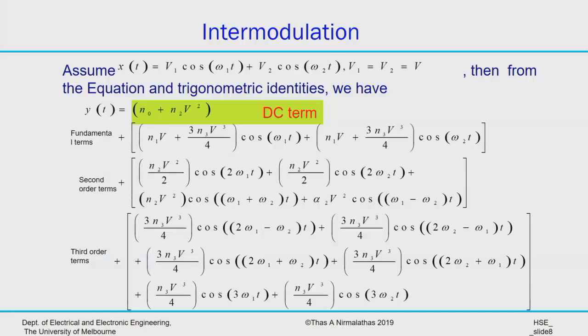All right. So as we expected, the coefficient in front of the gain of this fundamental signal is the same as what we had before. But here I'm trying to highlight there are more mixing of frequencies coming up. You only put in 2 frequencies, but because of the nonlinearity, we just created so many different frequencies.